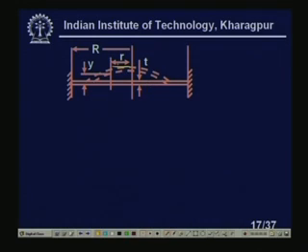T is the thickness of the diaphragm, and R is the radius of the total diaphragm, or the inside radius of the pipe. Almost it is equal to the inside radius of the pipe, and at any point from the center point deflection will be the maximum. These deflections we are calling YC. From the center at a distance r, the deflection we are calling Y. When r equals 0 at the center, Y equals YC.